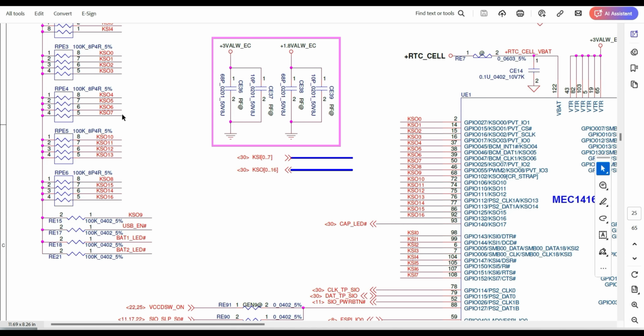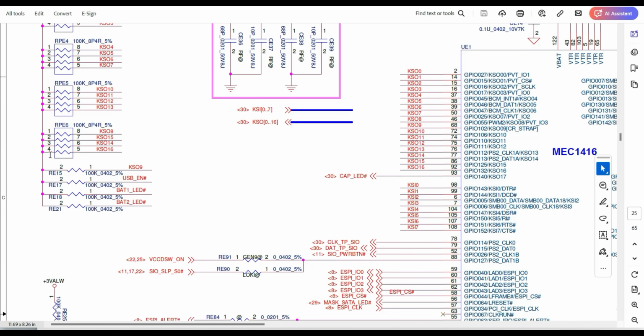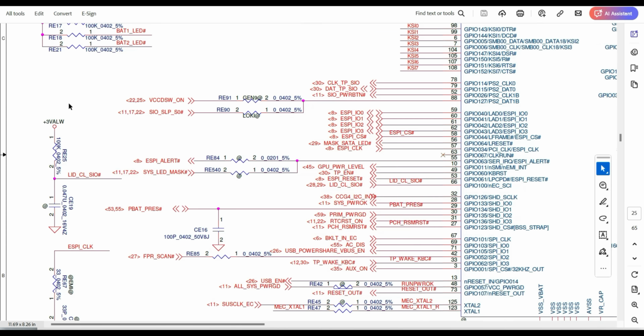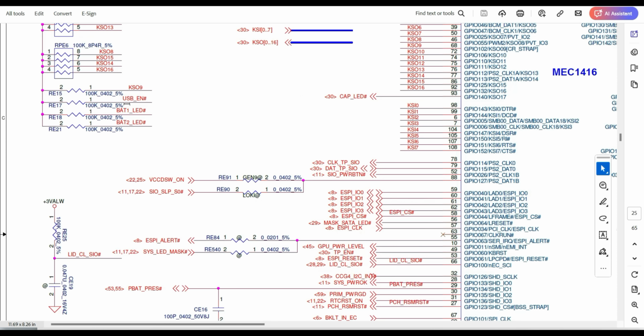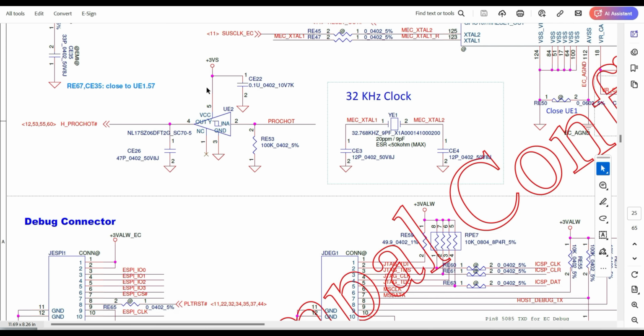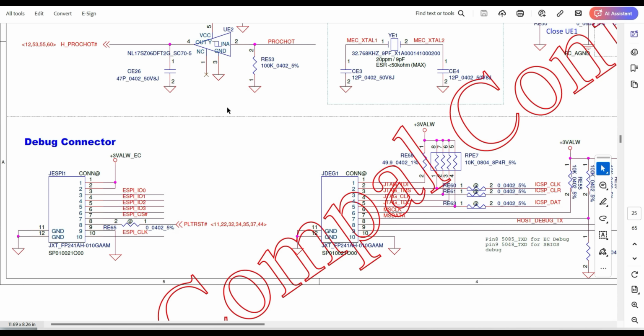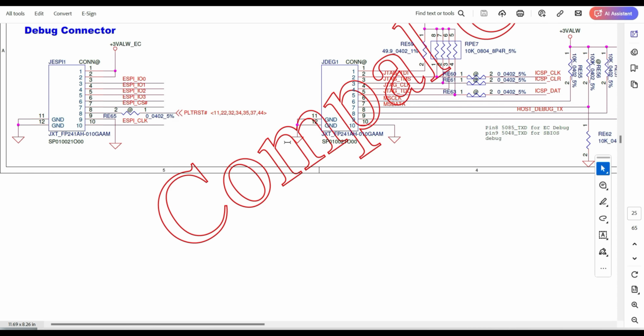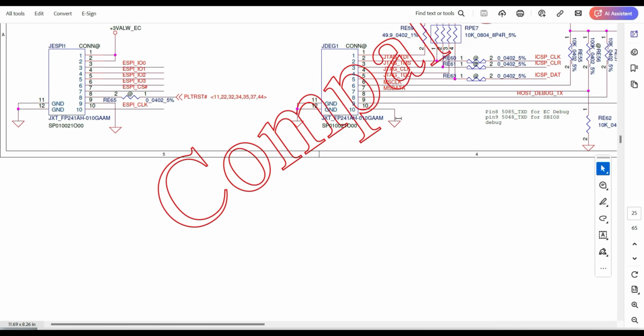Okay, here is a jumper, same thing. See, the same voltage will go here, to this particular signal. Here is the 100K, 0402 size, lid close hash. Hash means it may be 3 volts or it may be 0 volts depending on the active components connected to the destination part. Here is the pull down. Series, it's a jumper.